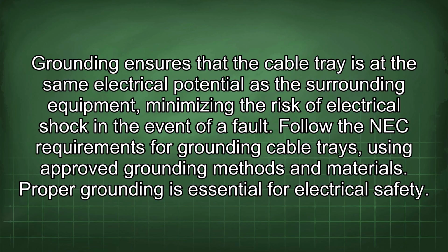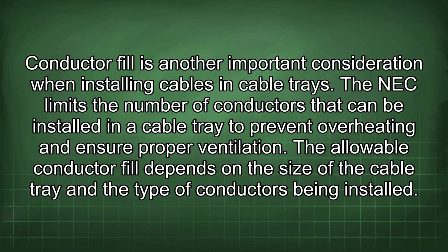Follow the NEC requirements for grounding cable trays, using approved grounding methods and materials. Proper grounding is essential for electrical safety. Conductor fill is another important consideration when installing cables and cable trays.